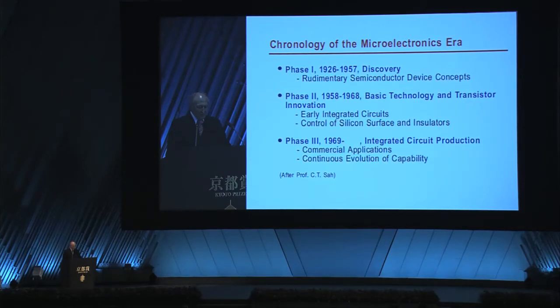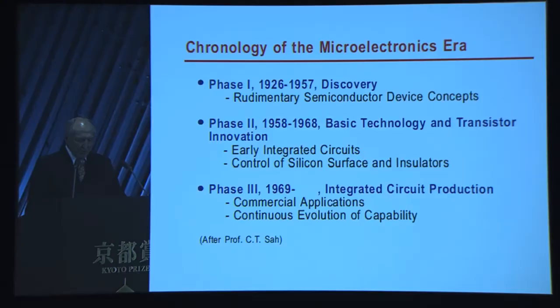What impressed me is fundamentally better about their approach was that they had a very simple memory cell, just a small square of magnetic material at the intersection of 2 etched copper lines. I was inspired to find something that simple for the technology we were developing. I went home that evening pondering analogies between magnetic circuits and electronic circuits. I considered the possibilities for using a simple capacitor as a basic memory element, storing a binary bit by charging or discharging the capacitor to two different voltage levels.